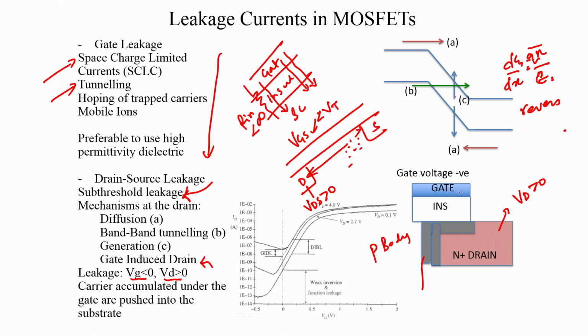And the hope is that there are no leakage currents through the source and drain. But if you watch the gate insulator, n type semiconductor region, what you have is a metal insulator semiconductor contact, with the metal having a lower potential. So, this would lead to several depletion regions. Firstly, you have the depletion region on the p side and the n side here, because of this p-n junction diode between the body and the n doped drain, and then you will now also have a depletion region that exists below this gate,